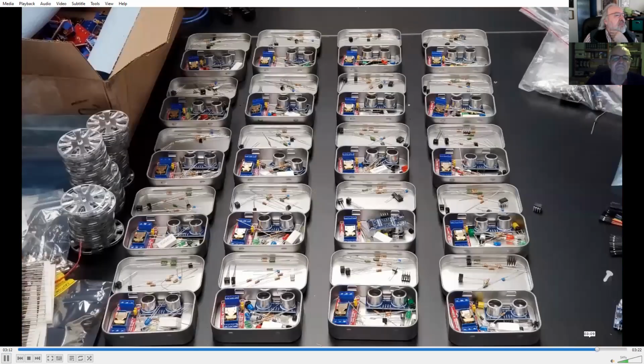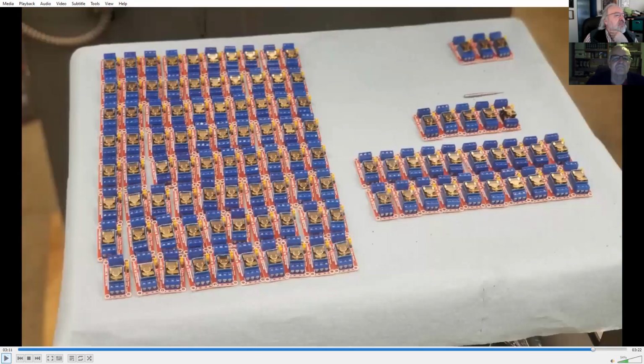So a lot of soldering. This is actually something I'm kind of proud of that I'd like to incorporate into the kits. Ken and I were discussing how we might be able to do this, but they've got these really nice relay breakouts, single pole, double throw relays with a little transistor to give them a boost from the 3.3. And what we do is we cut these off. So we might figure out a way to automate these on some of the CNC machines that Parallax has or that I have.